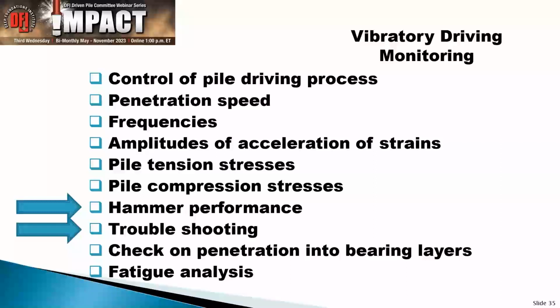And again, I cannot overemphasize the value of monitoring. Yeah, and again, comes back to plan, do, check, and act. Monitoring to me should be applied every single time that you drive a pile. Because once you drive a pile, you cannot look into the ground. You don't know what's happening below, and only if you take the measurements, you can figure out if something goes wrong, what's happening. And what I see, unfortunately, way too often is that something does go wrong.